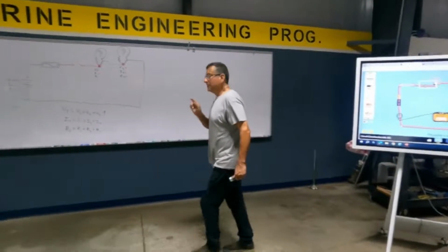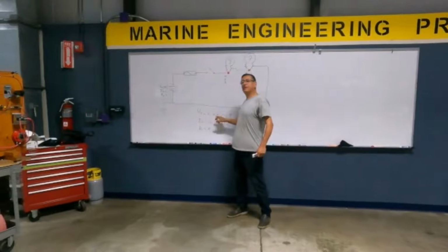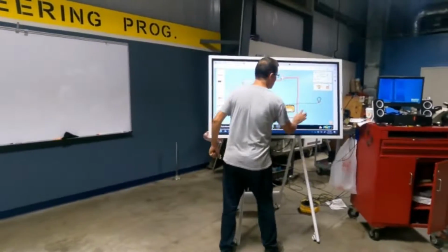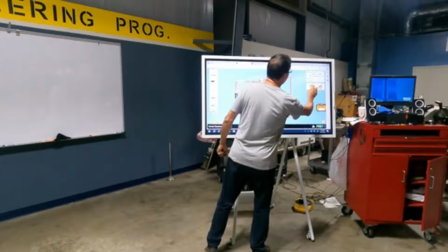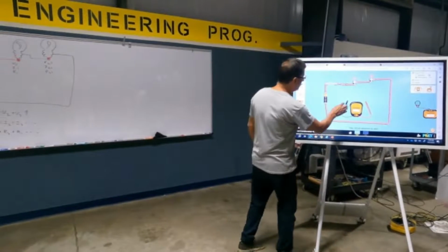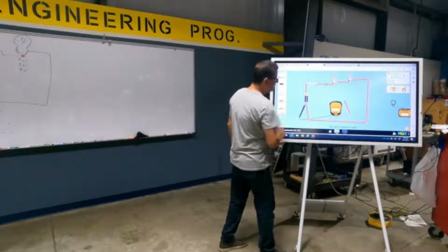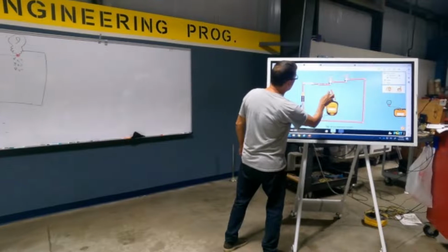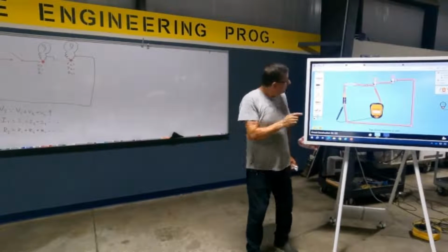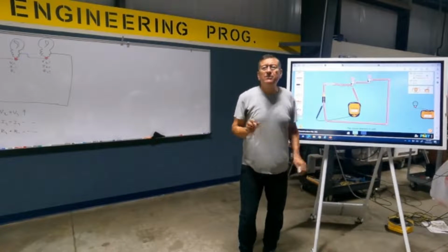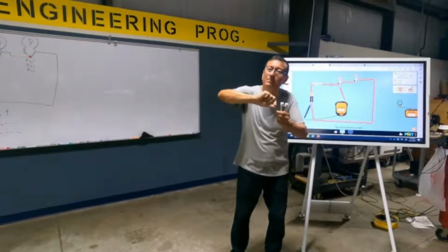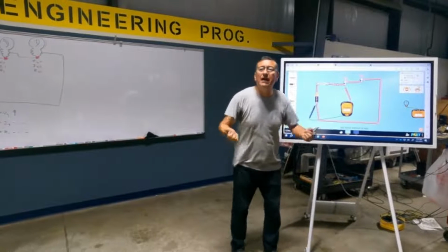What about the voltage? The total voltage is equal to this plus this. Let me check that. That was the intensity, and now we are going to play with the voltmeter. With the voltmeter, I am going to connect the negative here. How much will the voltage be at this point? It's 8.99. Here it is 9, but over there it is 8.99 because I have a loss of power, a voltage drop, because of the cable, some drag.